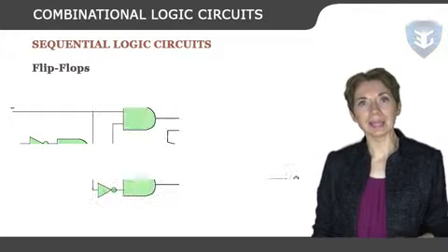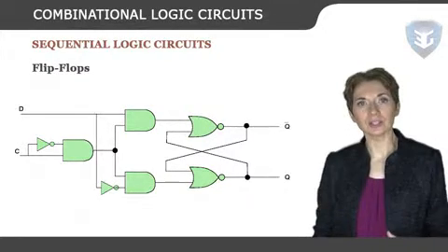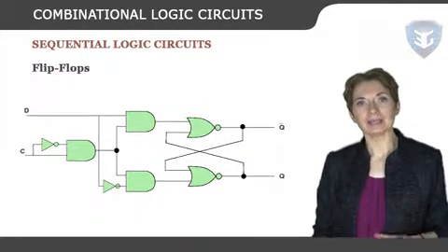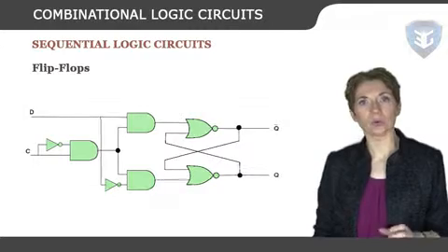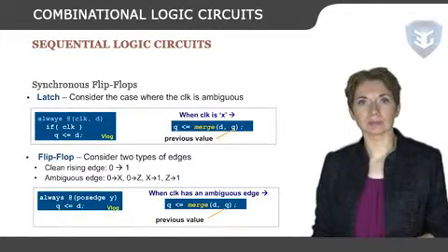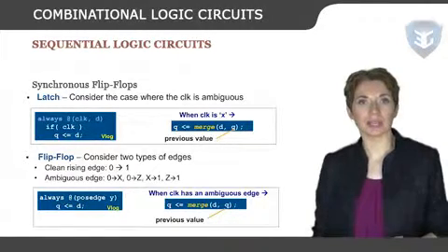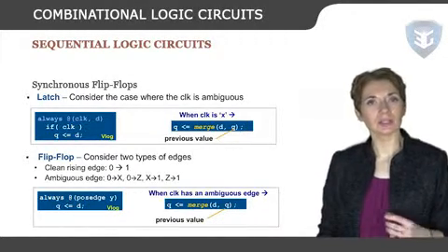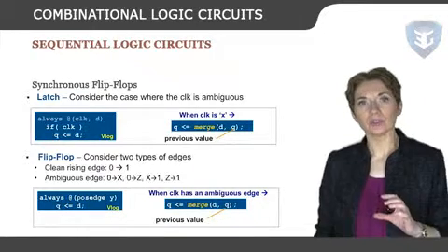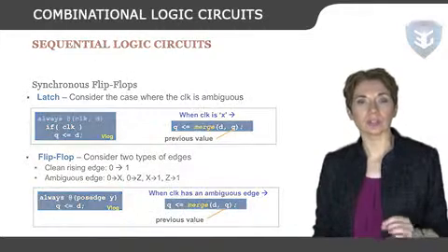Flip-flops. In the case of a latch with control input, when the control is enabled, the latch is in transparent mode. That is, its output changes its state according to the set and reset states. Synchronous flip-flops. In synchronous circuits, the inputs are pulses or levels and pulses, with certain restrictions on pulse width and circuit propagation delay. Therefore, synchronous circuits can be divided into clocked sequential circuits and unclocked or pulsed sequential circuits.